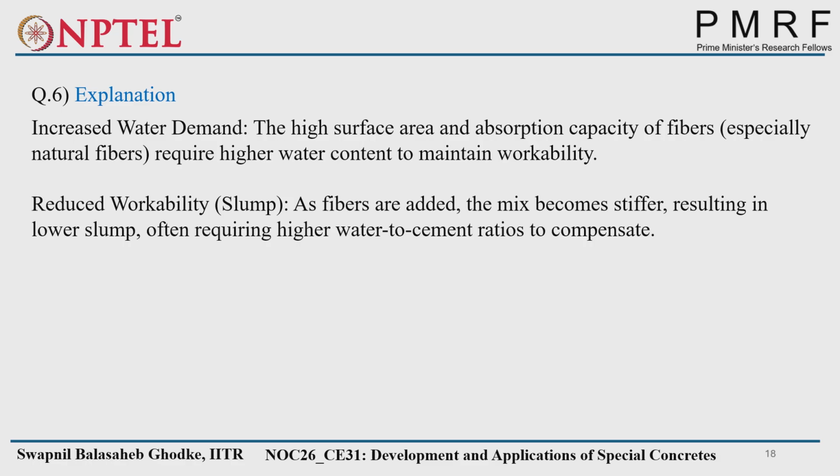If you see, suppose we have a flowable concrete and we add some fibers and mix it, you'll see that whatever flow you were getting, that flow will get reduced. To maintain the same flow, we have to add more water, or we have to add superplasticizer also.